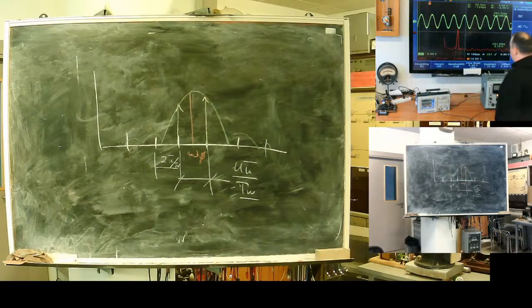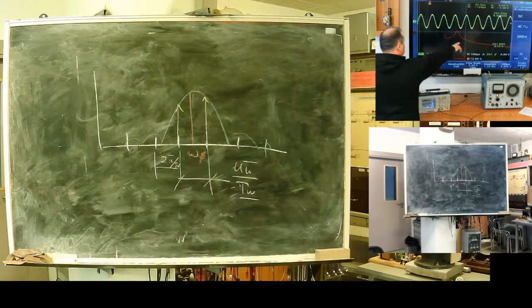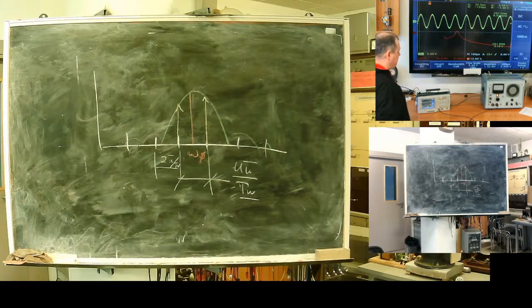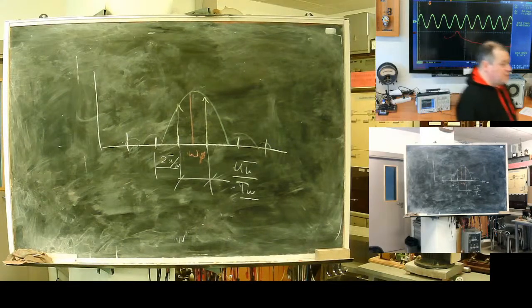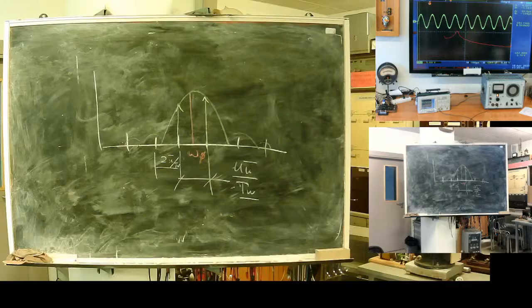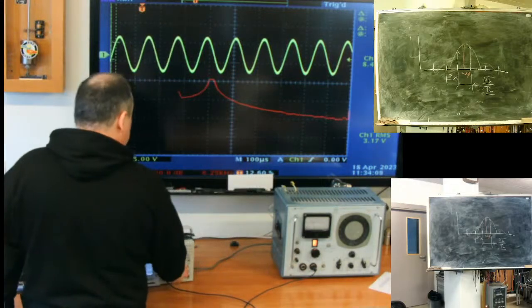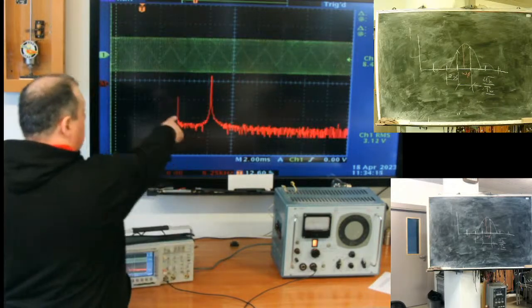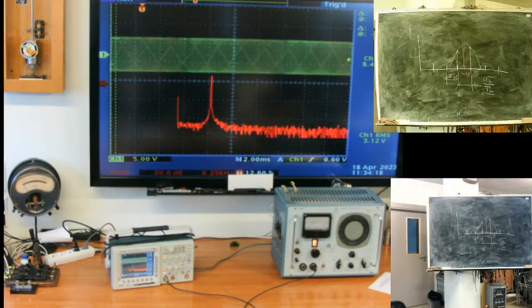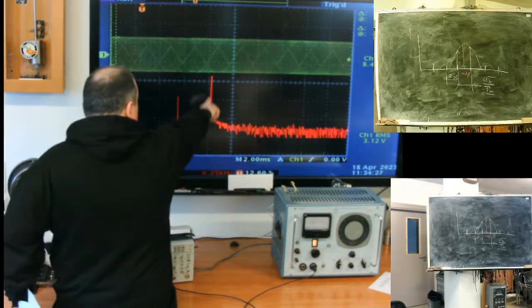Even on a bad case, here, bad case, the signal frequency is between natural lines of my instrument. Make a switch. Take a look, I'm changing the observation window. You see? It performs better. So the longer the observation window, the more samples I take into the Fourier transform, the better the result.